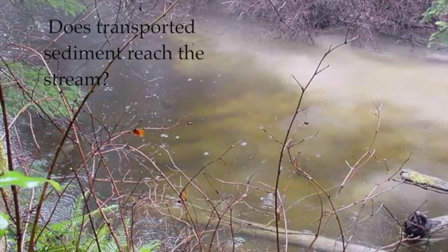Traditional GIS-based watershed management procedures, total area harvested, ECAs, the length of road, or the number of bridges have been used as indicators when evaluating hydrological impacts of human disturbance on a watershed. Unfortunately, if the level of management is not integrated into the analysis, the evaluation is useless for determining how to manage the watershed better. It merely flags the fact that a watershed has undergone human disturbances. What is important, however, is how the roads have been constructed and managed.